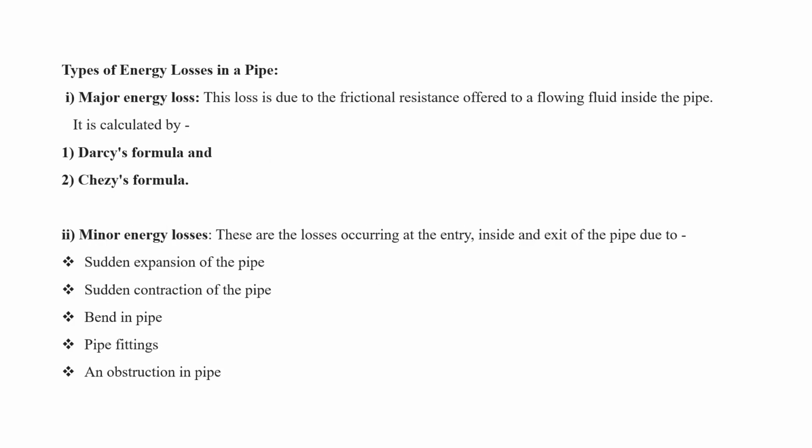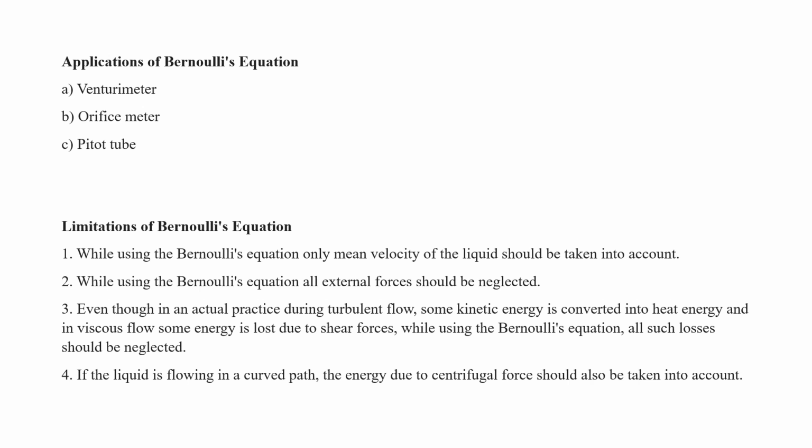Now, what are the limitations of Bernoulli's equation? While deriving Bernoulli's equation, some assumptions are made which are not practically applicable. The first one is, while using Bernoulli's equation, only the mean velocity of the liquid is taken into account, but practically it is not possible. Also, all the external forces are neglected, but practically they cannot be neglected.